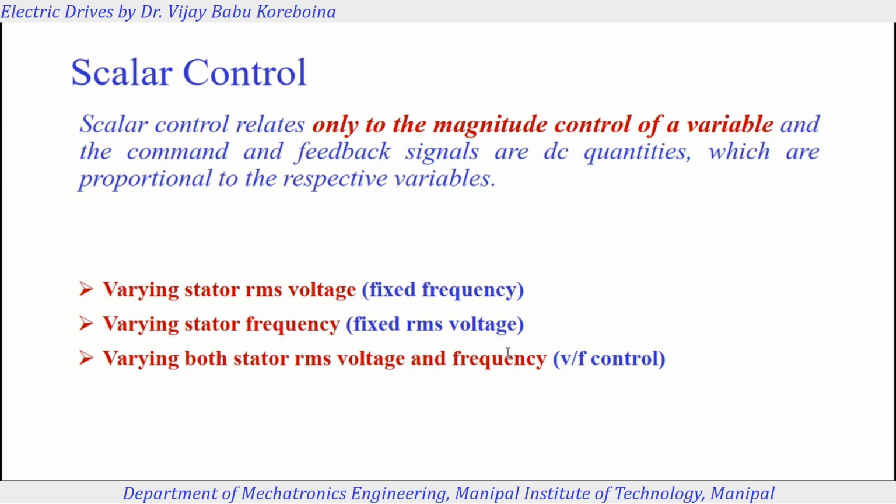But since you are not controlling the inside flux accurately, what will happen is that, for example, I'm changing the applied voltage, and the applied voltage should reflect in the current, and that current should reflect in the flux, and that flux should go to the resultant flux. So what we say is, you will find a sluggish response. That means you're not controlling the inner variable very fast. You're just controlling outer variables, and the dynamics will be slower. That's what we can see.